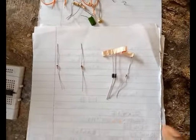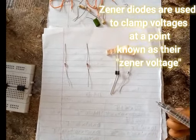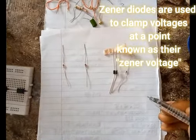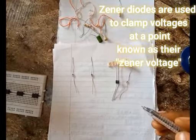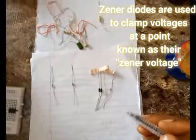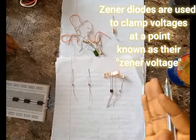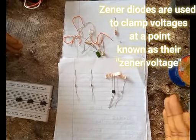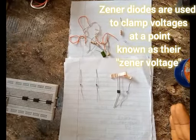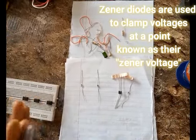Now Zener diodes generally are used to keep voltages. Their major use is to keep voltages at a particular point. They clip voltages at a particular point. If you put them in a circuit, what they will do for you is that if you have a higher voltage coming into that part of the circuit and you need a particular voltage to come out to feed another part of a circuit, you make use of Zener diodes. The Zener diode will help you keep it at a particular voltage regardless of the voltage coming at the input side.